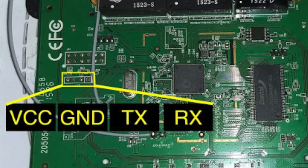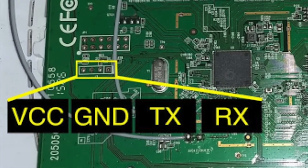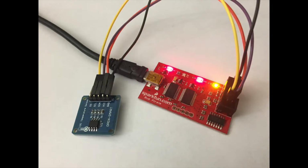Once you've finished mapping which port does what function, now you're ready to solder in connections into the UART ports to communicate with your terminal. If soldering seems like too much of a commitment, the Bus Pirate allows you to create non-permanent connections with the device just by plugging in your device to the UART ports.